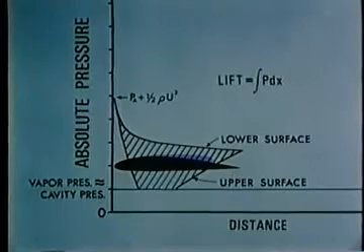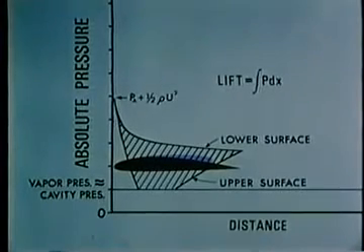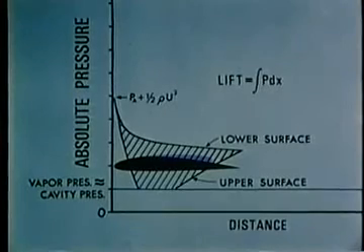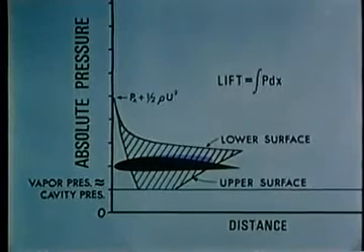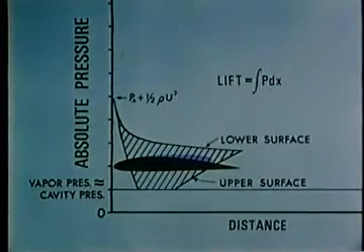Since the pressure on the lower surface does decrease, the lift drops. Actually, as cavitation develops, the shape of the pressure distribution changes somewhat. The resultant pressure distribution is such as to cause an increase in drag. Thus, hydrofoils, and for the same reasons, many hydraulic machines, which are designed for efficient subcavitating operation, lose efficiency when cavitating.